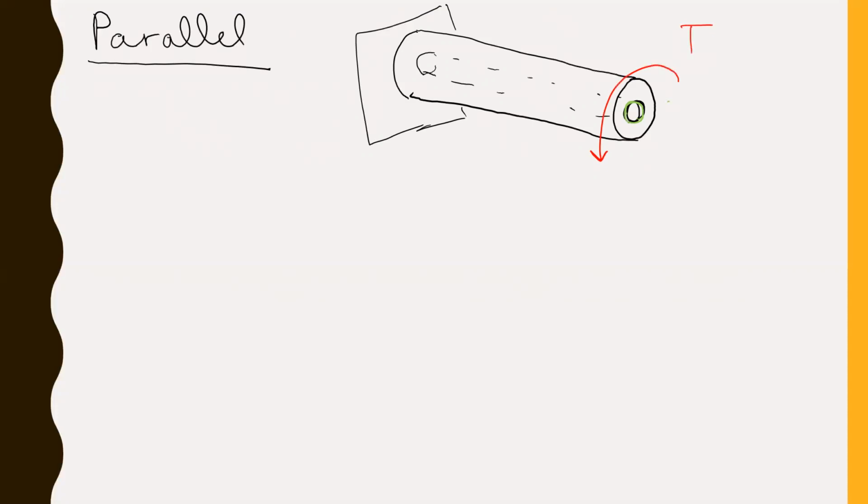Torque. And we know that there are some material properties of these two members. We will make the outside member member 1, which means that outside member has some G1 and J1 value, and the inside member has a G2 and J2 value, where G is a constant that is dependent on the material, and J can be computed using a function that depends on the geometry.